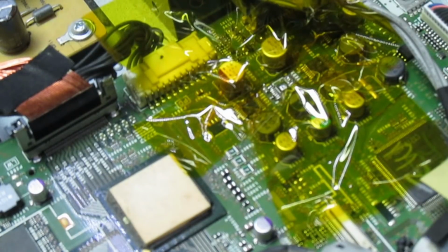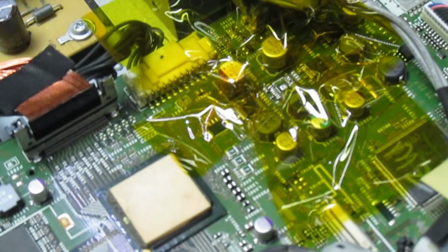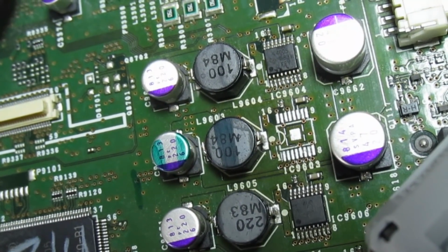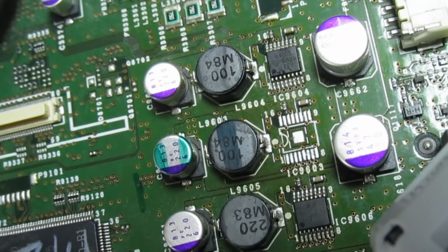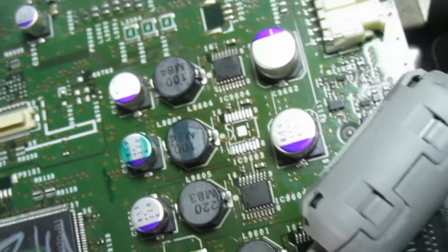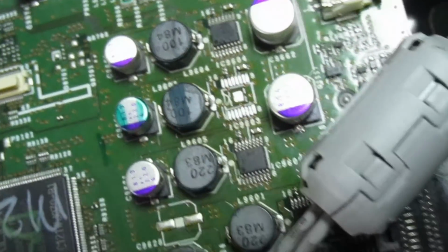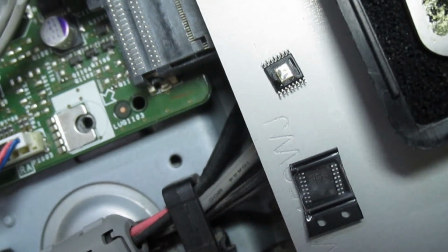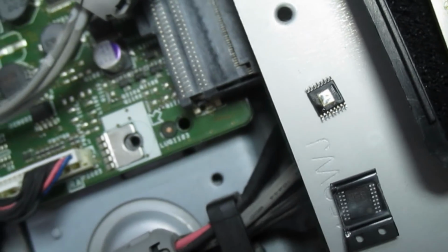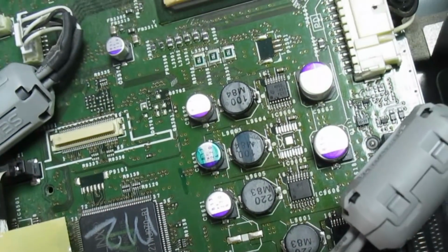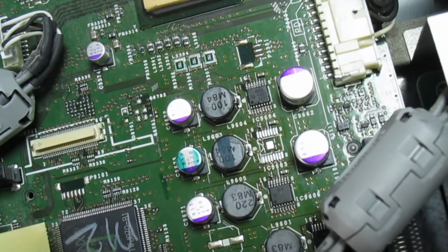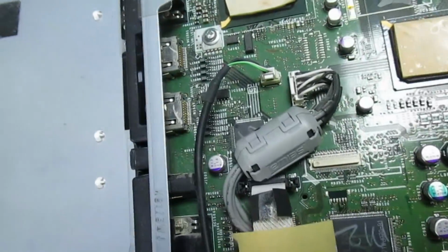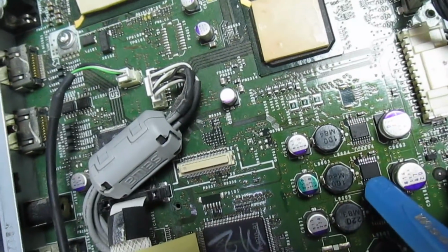And there we go. Right, well, that wasn't very keen on coming out, but you can see the problem. The little pad in the middle that's soldered to the bottom of the chip. So anyway, we've got it out. Let's have a look. That's the old chip there. That's the new one ready to go in. Fitting this is the reversal of taking out the old one. So let's just pop the new one in. Right, so that's the new chip fitted there. The middle one there, as you can see.